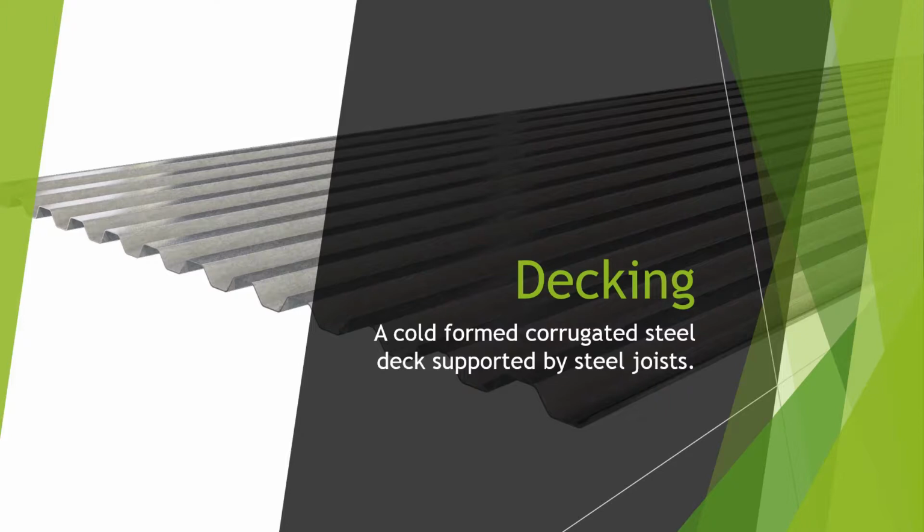Unfortunately, though guys, this is when iron workers get a false sense of security when this decking is laid. The decking makes you think it's safe to walk around and not tie off with fall protection, which is a big no-no for iron workers and any other trades that are now on the roof doing their work. There's usually hole openings when we have decking laid down, and sometimes decking is not welded. So then there's a big opportunity for falls to happen, unfortunately. Also, workers on decking have been thrown off buildings.